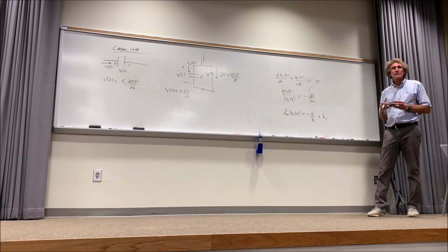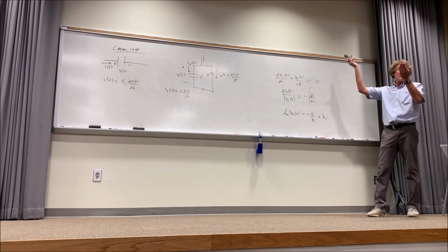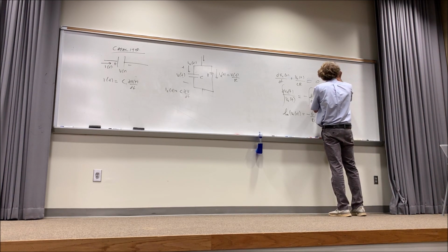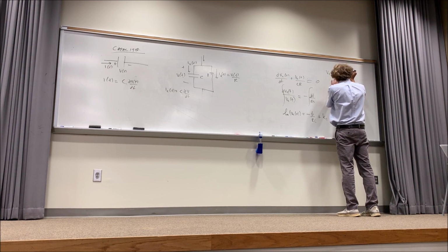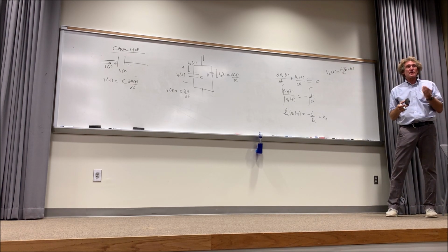All right, now, after that, the only thing I do is I want to solve for V_C of t. So I have log of x equal a constant. To find out what x is, take everything to e to that power, right? So then I get V_C of t is going to be equal to e to the minus t over RC, right? And it's plus k in the exponent. Do y'all agree with me here? I'm going through this simply and slowly. I'm not doing anything crazy.